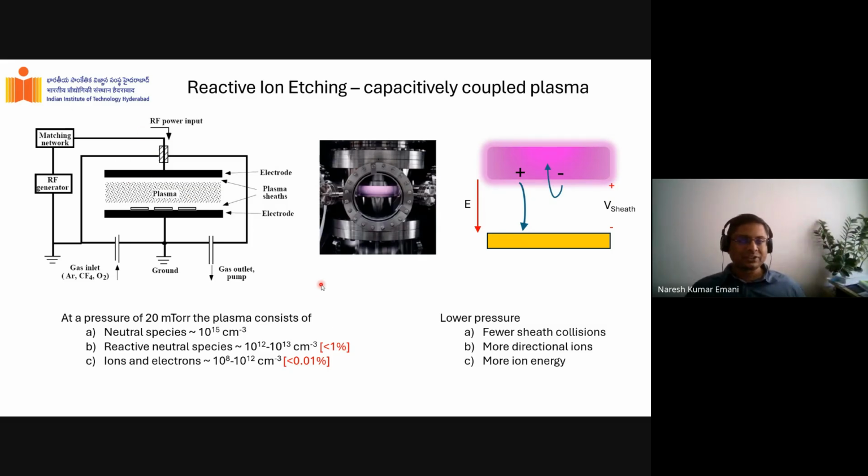Okay. When you have this chamber, it is not enough to just have plasma. There's something else that happens. Because we have an electrode, which is, let's say, a cathode at a low potential, electrons can quickly get accumulated. Wait, I'm sorry. The electric field is this way. So positive ions will come forward like this. So there is a small region where essentially the electrons will quickly go into the substrate and the positive ions are left on the top, right? They don't move as fast, we said, right?